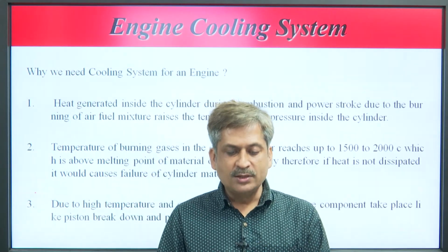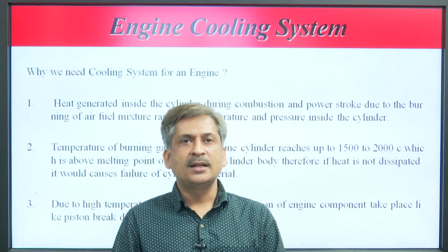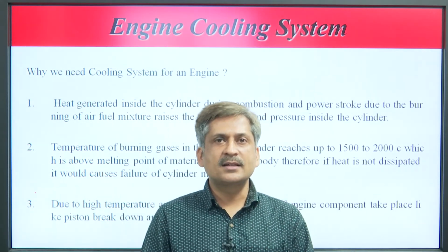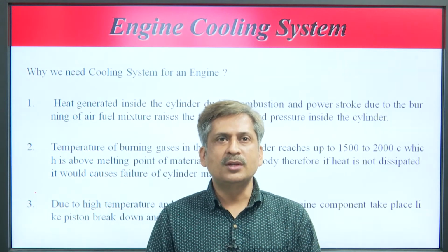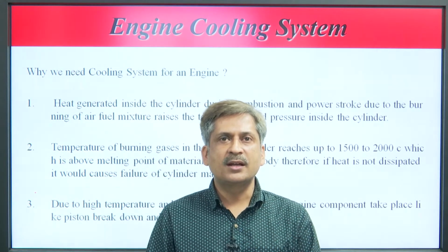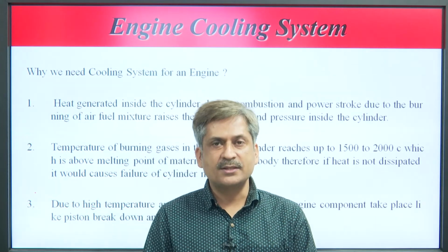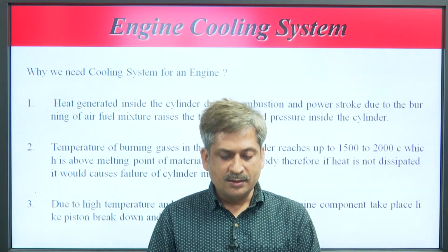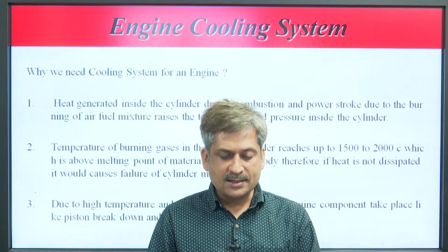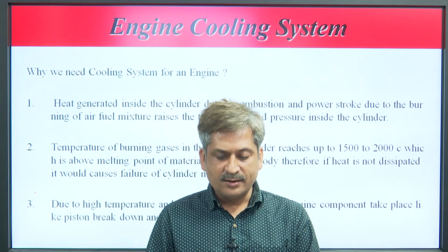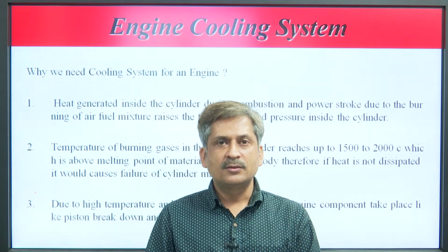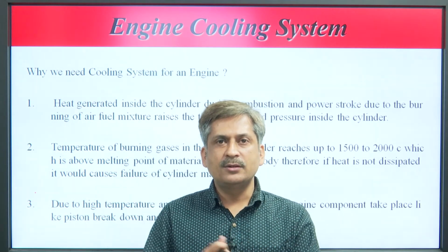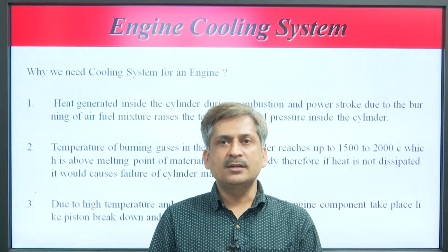So, why do we need a cooling system for an engine? Heat generated inside the cylinder during combustion and the power stroke, due to the burning of the fuel-air mixture, raises the temperature and pressure inside the cylinder. Second, the temperature of the burning gases in the engine cylinder reaches very high values.